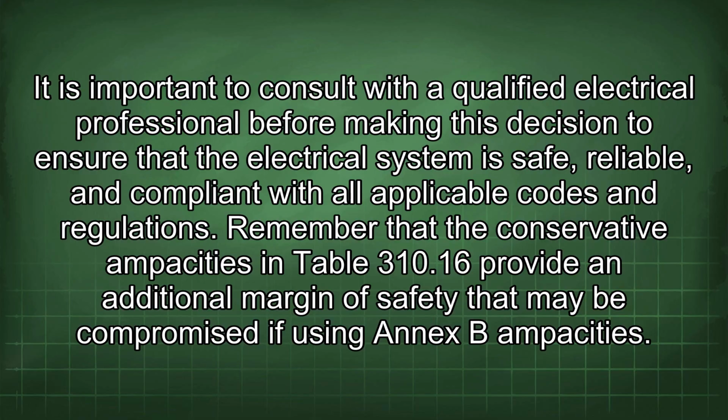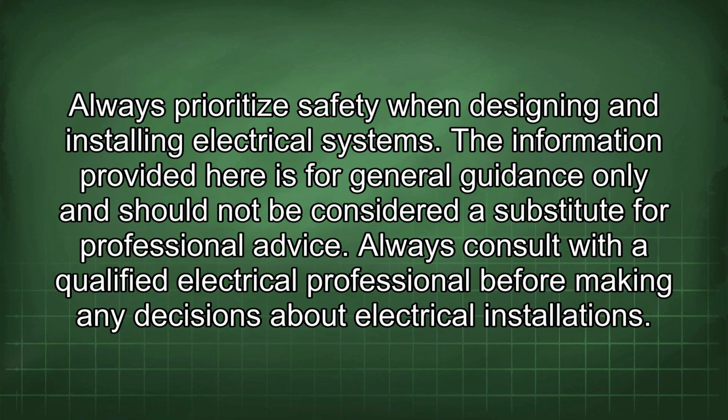Remember that the conservative ampacities in Table 310.16 provide an additional margin of safety that may be compromised if using Annex B ampacities. Always prioritize safety when designing and installing electrical systems. The information provided here is for general guidance only and should not be considered a substitute for professional advice. Always consult with a qualified electrical professional before making any decisions about electrical installations.